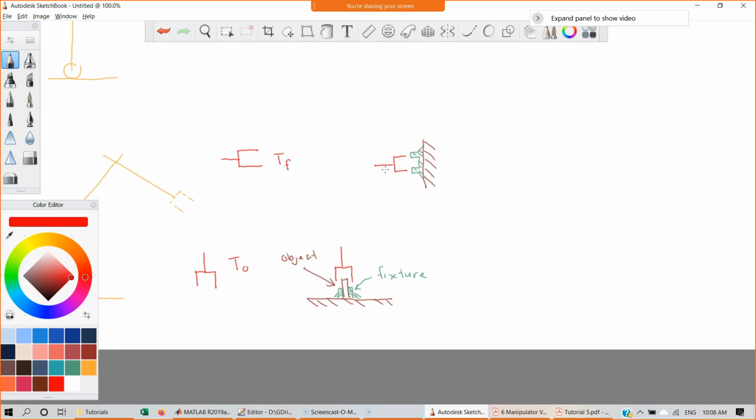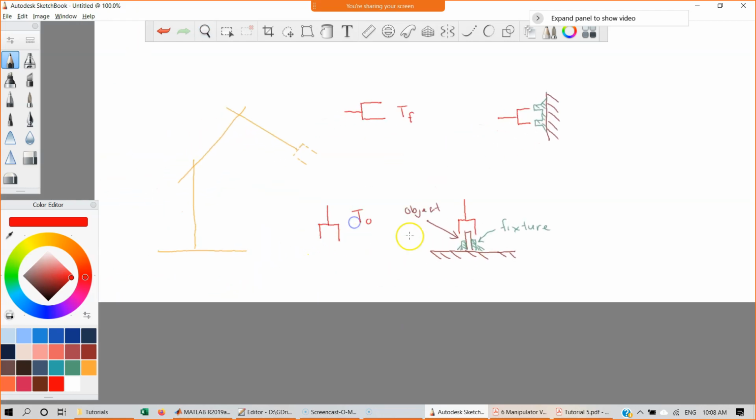And this is exactly why I need to design a trajectory. So this is the importance of having a robot arm trajectory, because I want the end effector of my robot arm to begin in one pose, position and orientation, and end up in another pose. And we have to design the H1, H2, H3 for every joint.